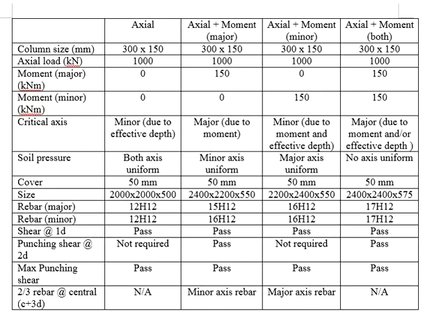That's why if you observe the other references, they only check for one axis, which is the more critical axis. Therefore, if you have moment in the major axis, you only need to check for the major axis. Whereas if the moment is in the minor axis, you can simply check the minor axis. Now the question here is whether you can design for the critical axis based on the amount of reinforcement bar required, and adopt the same for the other axis.